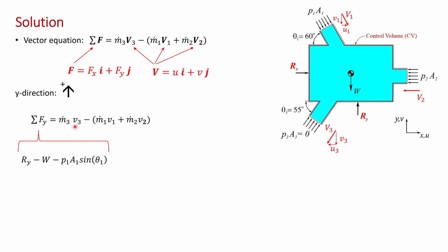Next, we can move on and express the y components of velocity here, v1, v2, and v3, in terms of capital V's, in terms of the velocity vectors that were given in the problem statement. So as we did before, lowercase v3 equals uppercase V3 sine theta, because we want the vertical component, but it's negative because it acts in the negative y direction.